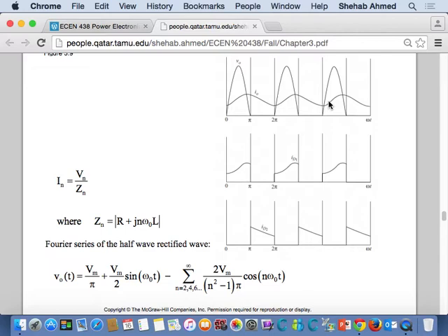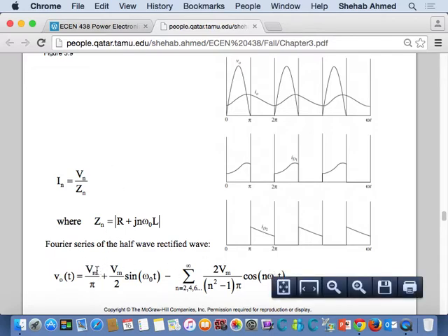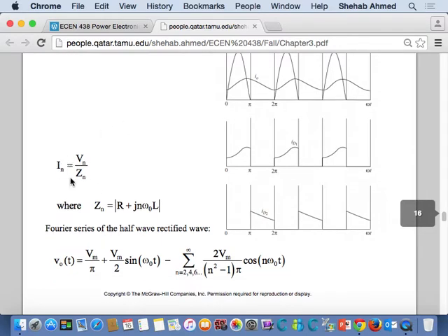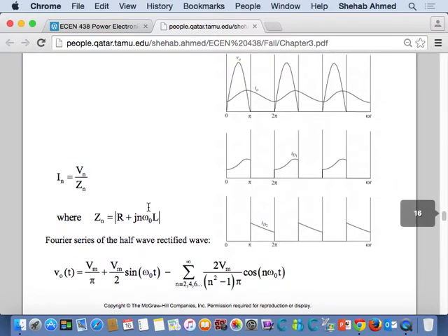So if you have an equation for the voltage on the output, and you know your impedance, R and L values, then you can use the Fourier series to take each component of voltage and every frequency's corresponding impedance and find the corresponding value of harmonic current. So you can find the Fourier series of the current, or all the components of the current, the Fourier series expansion of the current, from the Fourier series expansion of the voltage and knowledge of your impedance. Everybody's okay with that?